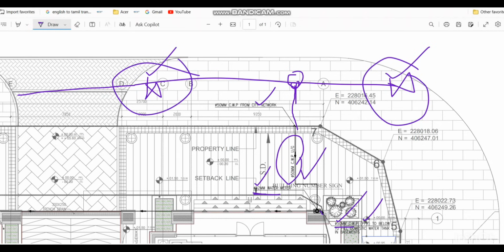with the existing line. After that we have to drain the complete water which is located inside this pipeline. We have to drain the complete water, then only we are allowed to make the proper hole. Then we will make the connection, the tie-in connection with our services.